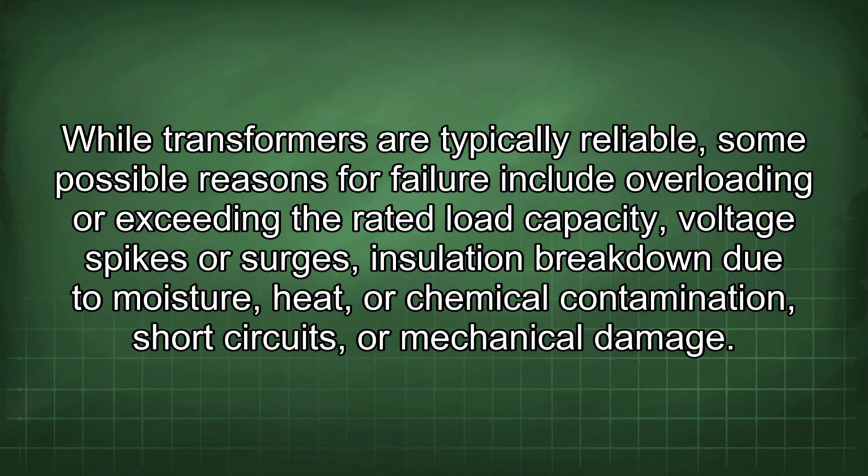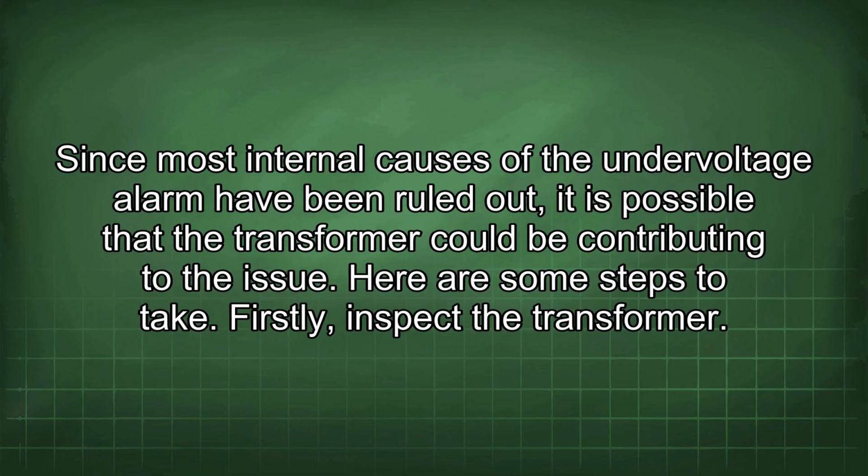While transformers are typically reliable, some possible reasons for failure include overloading or exceeding the rated load capacity, voltage spikes or surges, insulation breakdown due to moisture, heat, or chemical contamination, short circuits, or mechanical damage. Since most internal causes of the undervoltage alarm have been ruled out, it is possible that the transformer could be contributing to the issue. Here are some steps to take.